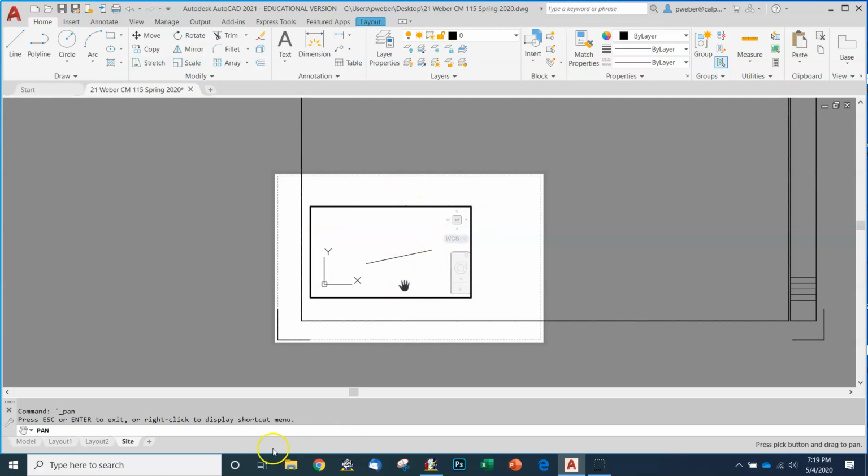Now I'm in the viewport. Let me come back out of the viewport to the top surface of the paper. Because right now, where's my hand? Here's my hand. If I move my hand up above here, I can't see the hand anymore because it's hidden underneath. It's in model space. But the top of this paper, it's paper space. So let me right click and go exit.